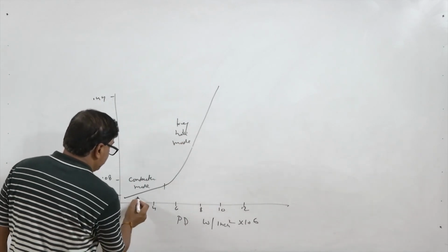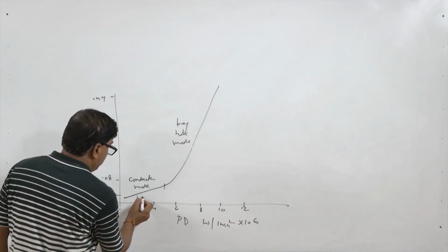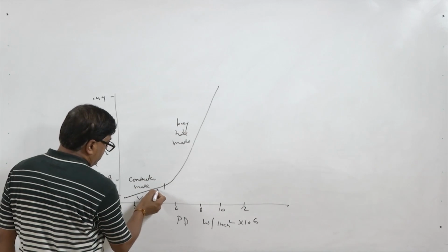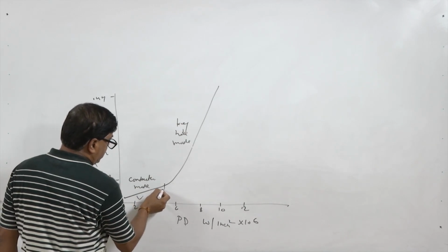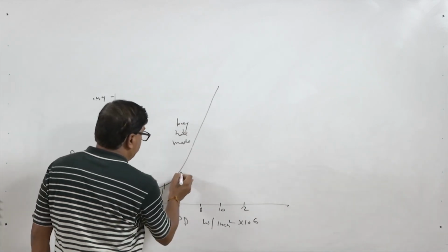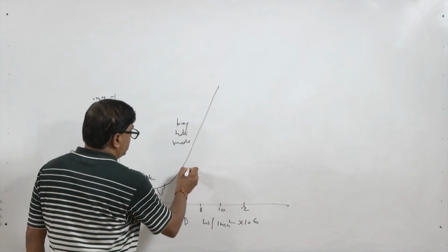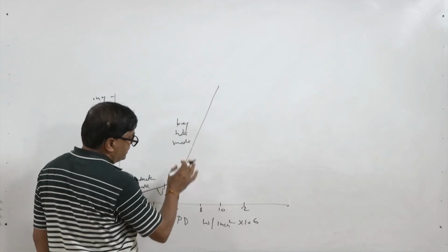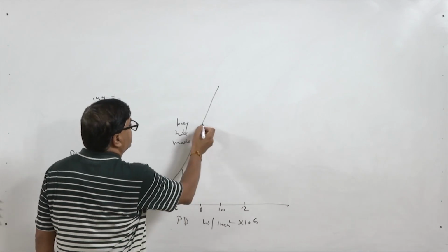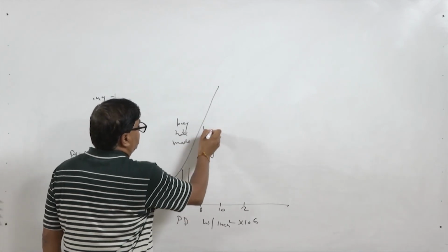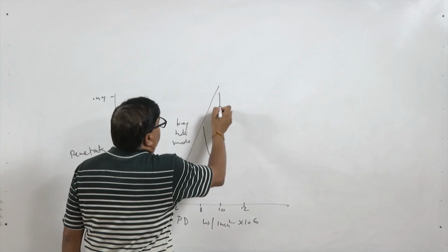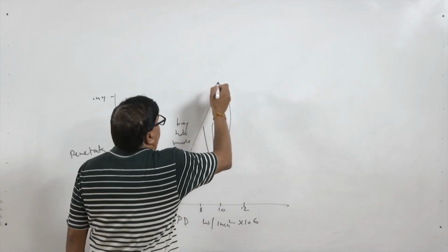Here the width is large and penetration is limited; width and penetration increase, but thereafter the width does not increase much, while the depth of penetration keeps on increasing without an increase in the width of the weld.